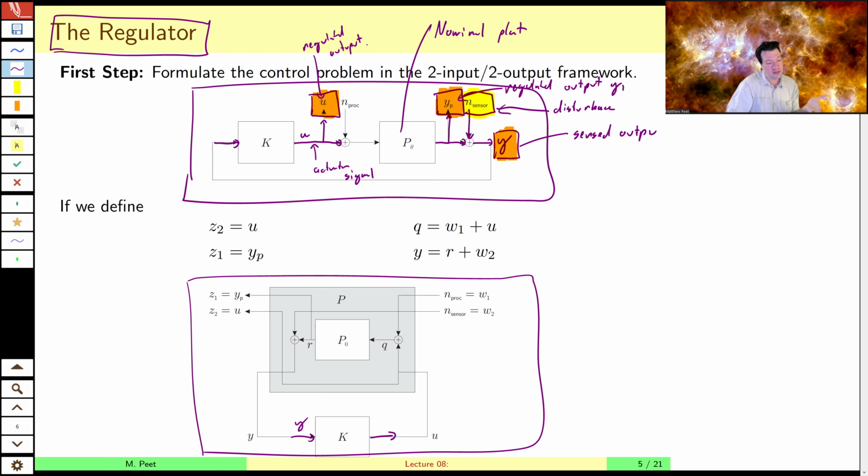in any practical control system, our actuation authority is limited. This can be due to things like saturation of the actuator signal, or maybe the fact that we just don't want to break our actuator. Remember, actuators are physical mechanisms, and if you send them a really strong input signal, they will either break, break the plant, or saturate and not do what you expect.